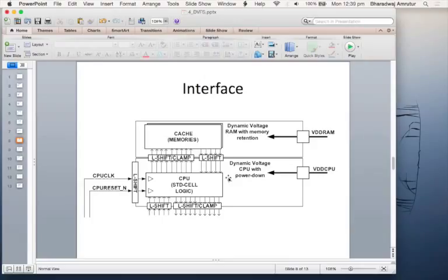Okay, so this is as far as the voltage. We'll also see, but we'll cover that later when we talk about power gating and so on, that sometimes you might want to retain the state even inside this. There might be registers. Because you might have multiple power down states. You might be in a standby state, then a hibernate state, or a suspend state. Depending on which state, you go deeper and deeper into a lower power mode, right? The ultimate is this: I just disconnect the supply, and there is nothing there.